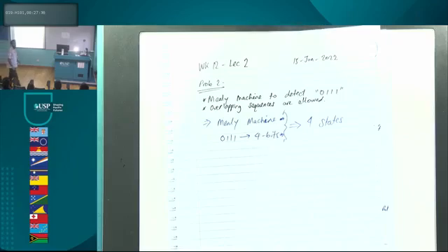All right. But what if it was a Moore machine? If the question was 0, 1, 1 and build a Moore machine? I hope you're noting this down. This is a very fundamental difference. You would need 3 initial states plus 1 state to take care of the output, 1 final state. So it's 3 plus 1. For Mealy, the answer is the number of bits; for Moore, plus 1. So in Moore, are there any unused states, if this question was Moore, 0, 1, 1? No.